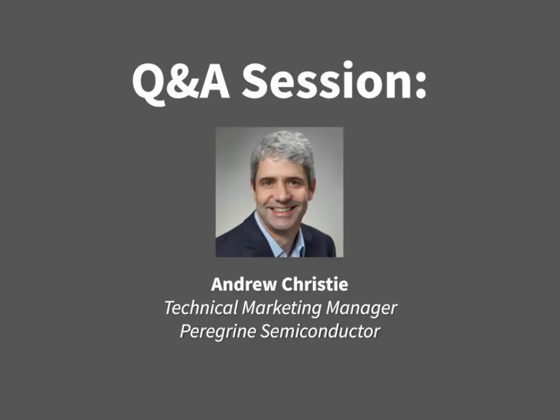Okay, our first question is, what semiconductor process is being used for 28 gigahertz power amplifiers? The 28 gigahertz, I assume. So for 28 gigahertz, we're using Peregrine's UltraCMOS process. For this application, it's an SOI process, so a CMOS on insulator process.